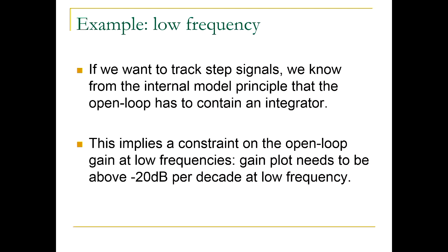So the controller in particular should contain an integrator, if the plant doesn't have one already. This we learned from the internal model principle. So what does this imply? It implies a constraint on the open loop gain at low frequencies. The gain plot needs to be above -20 decibel per decade at low frequency.